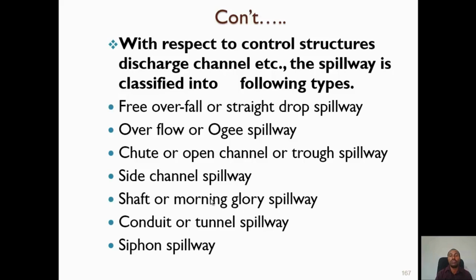Okay, with respect to control structures, discharge channel, etc., the spillway is classified into the following types. With respect to the discharge channel, that is, hydraulically, what flood magnitude it can convey: you have free overflow or straight drop spillway, overflow or Ogee spillway, chute or open channel or trough spillway, and side channel spillway.